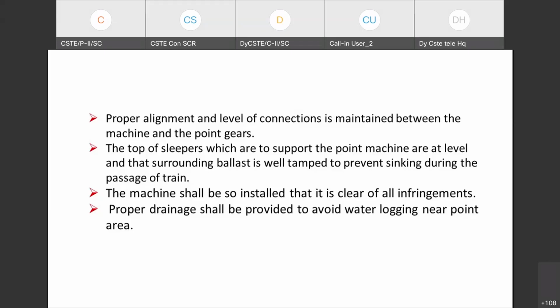The point machine maintenance should be done properly, and adjustment should also be done properly from the safety point of view. There are several cases in our railway and other railways also arising from maintenance. Whenever the point machines are taken for maintenance, sometimes there were cases where the work was done without disconnection of the point machine.